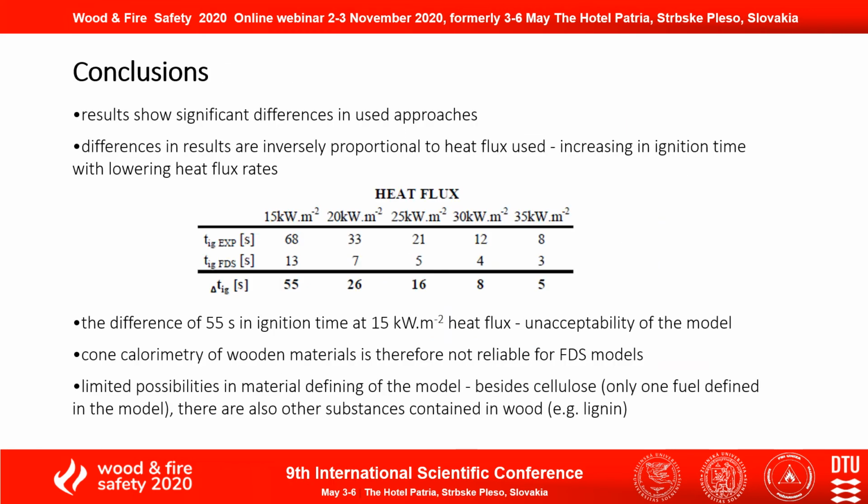Comparison of experiment and model results shows us quite significant differences in these approaches. Ignition times estimated from the model acquire distinctly lower values compared to laboratory measurements. Differences in results are inversely proportional to heat flux used, increasing in ignition time with lowering heat flux rates. Results are shown together in the table.